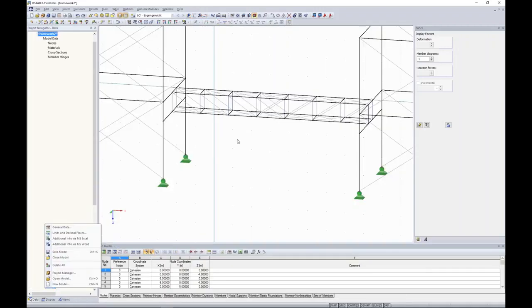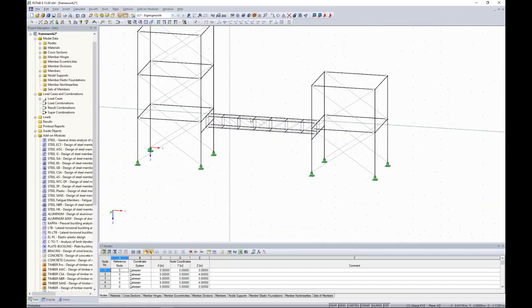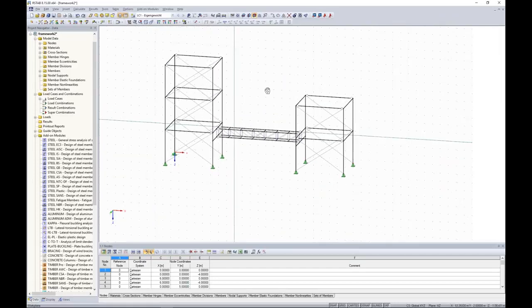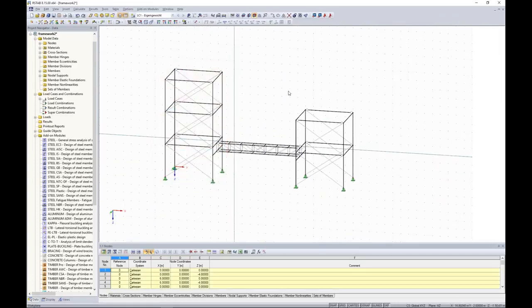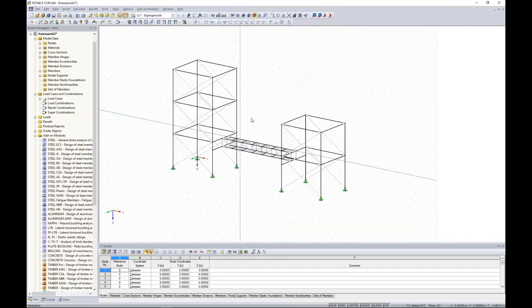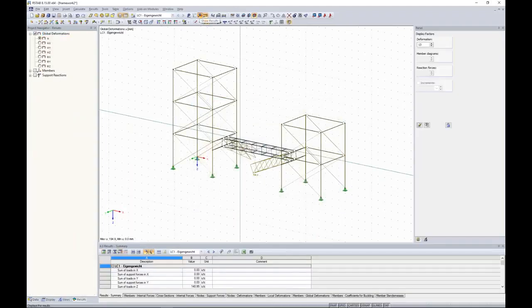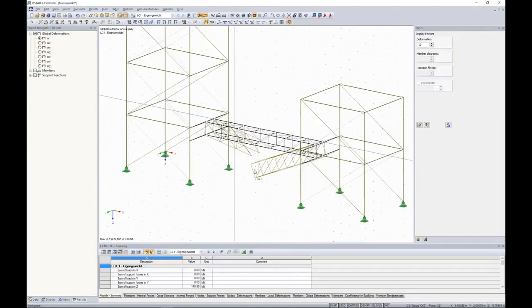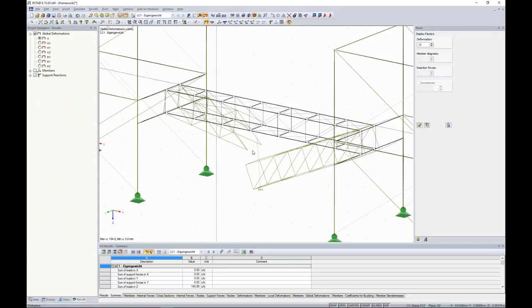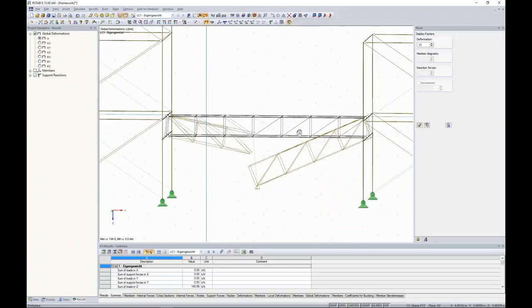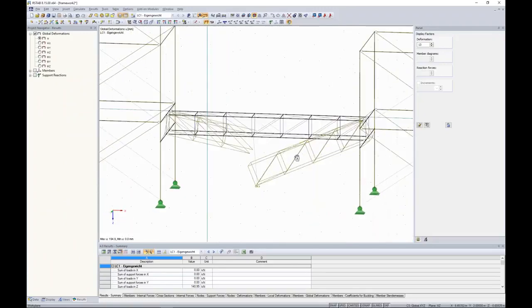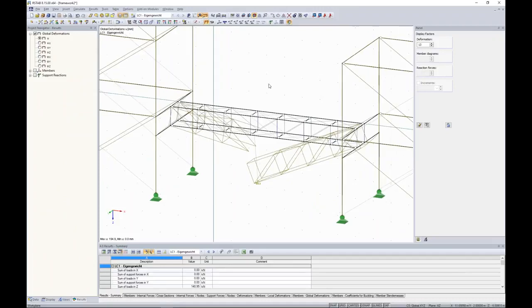That's framework number 2. It's the same framework on the left side and a smaller one on the right, and these should be connected with this cable duct, and you can just try to calculate the self-weight load case. And as you see in the graphic, the deformation looks quite strange. It looks like the cable duct is actually not connected. And what's the reason for that?